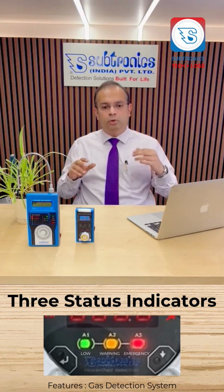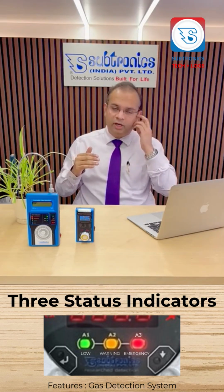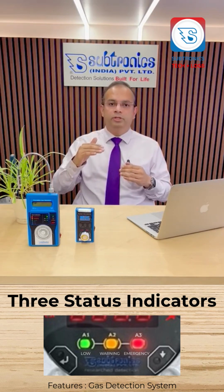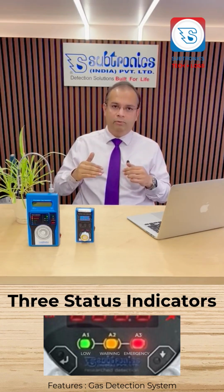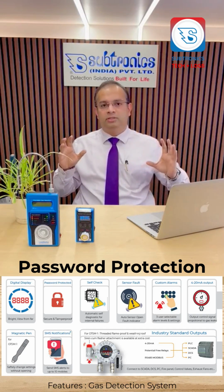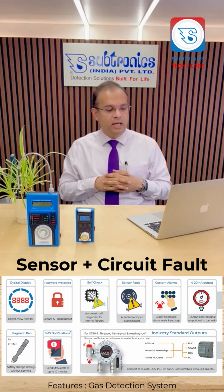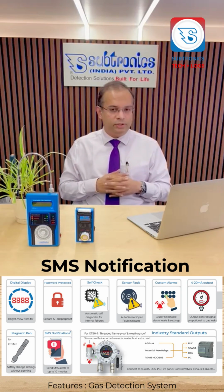Usually in the market, we have two-step alarms, level 1 and level 2. Most of our panels have three, just in case you need an early alert for the first step. We give it in the range of green, yellow and red, or low, medium and high, or you may call it alarm 1, alarm 2 and alarm 3. Usually all these are programmed. You should make sure that the systems have password protection. No layman should be able to tamper with these devices. So these are the typical features you find in a gas detection system.